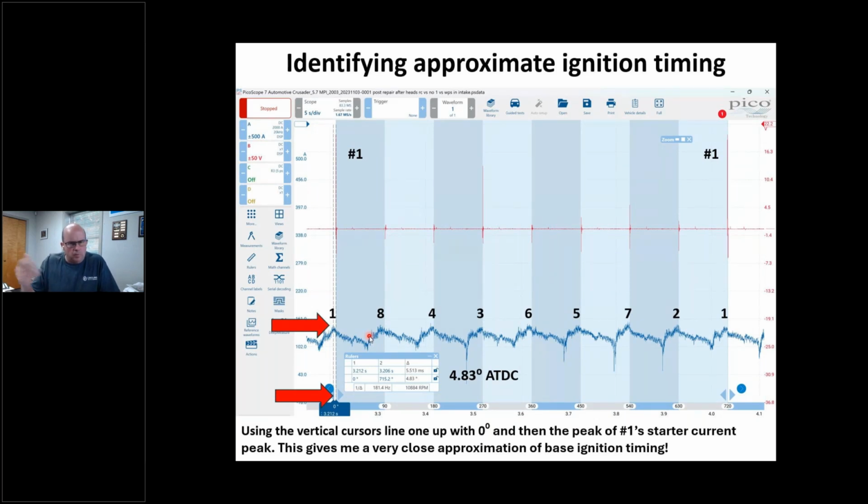Okay. So they're a Pico scope shop. And he called me. He says, hey, Chris, remember you're talking about checking ignition timing? And over the phone, I walked him through this test. He sent it to me. I said, hey, dude, you got something going on with your ignition timing. I said, where is that? He goes, well, there's magnets in a flywheel nut. I said, what's there? Is it a keyway? Is it a pin or whatever? He goes, it's a key.